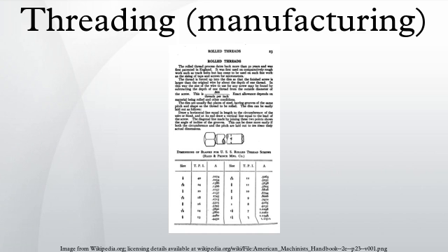Inspection. Inspection of the finished screw threads can be achieved in various ways, with the expense of the method tailored to the requirements of the product application. Shop floor inspection of a thread is often as simple as running a nut onto it or a bolt into it.